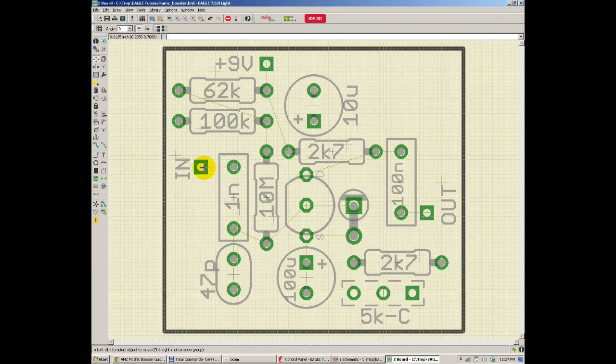Also, I like to route my signal traces on the bottom and have my supply voltages and supply signals on the top. Again, you can do it the other way. Anyway, it's good. You are not designing high frequency PCBs or radio frequency ones that require a lot of work and have a lot of technology behind. So for this PCB, just start and route.